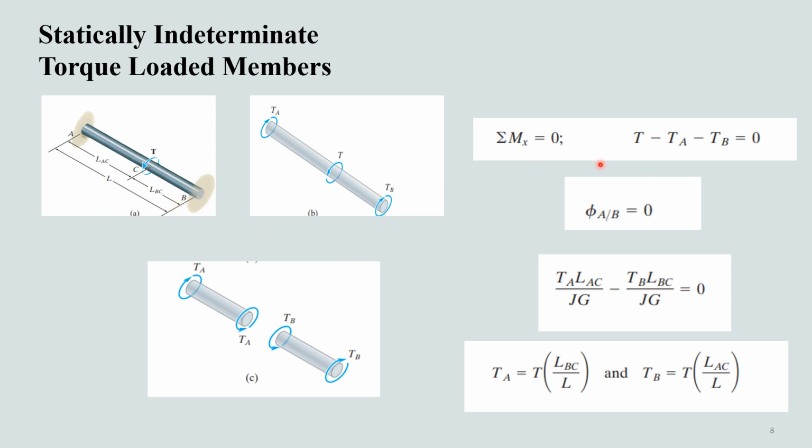So whenever we encounter this problem where the equations of equilibrium are not sufficient to give us the unknowns, we have to consider some additional equations, which are usually called the compatibility equations. These equations are derived by the requirements of fulfilling the kinematic conditions.